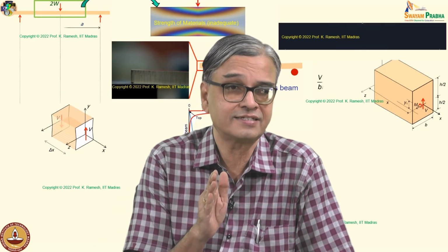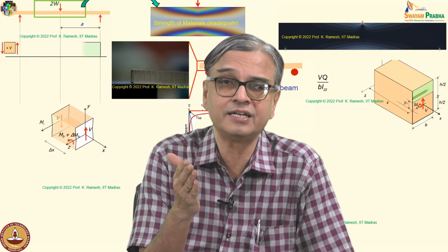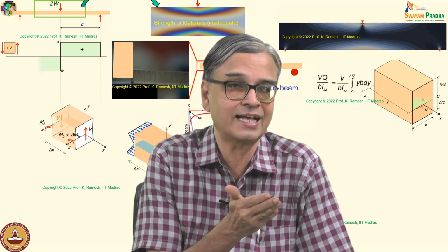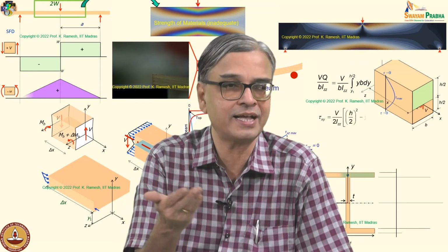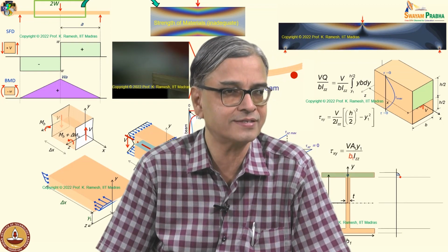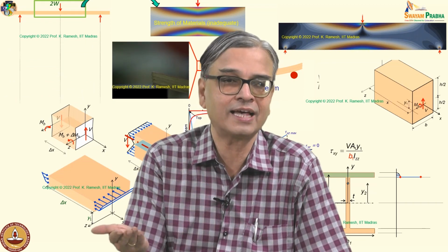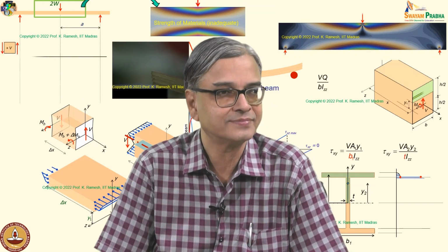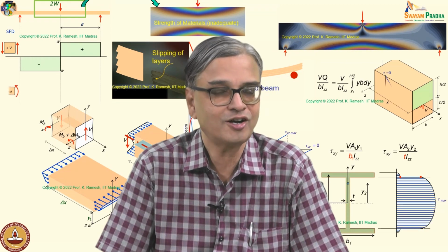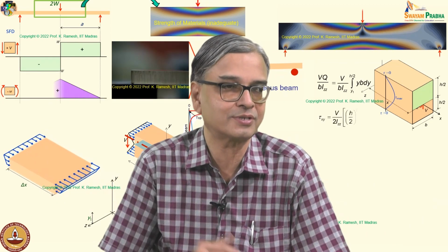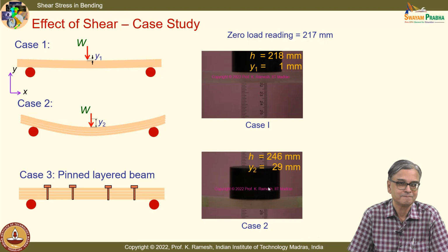See, yesterday I said I have to double the load carrying capacity of the glass plate. And I said from a design perspective, I can make multiple options. One option is to buy another glass plate, put on top of it. Another option is increase the thickness of the glass plate. The third option was put one more support. After this experiment, what would you say about putting another glass plate? It's not found to be effective.